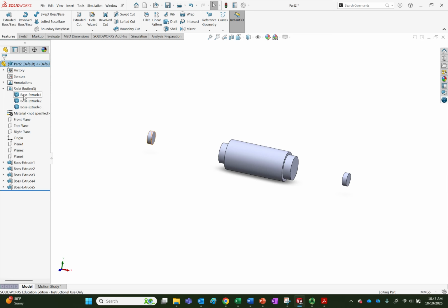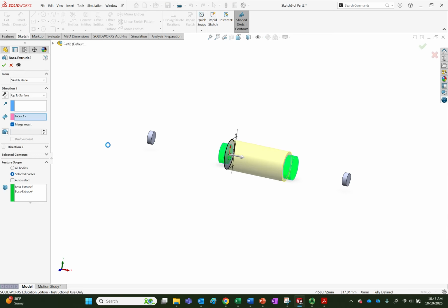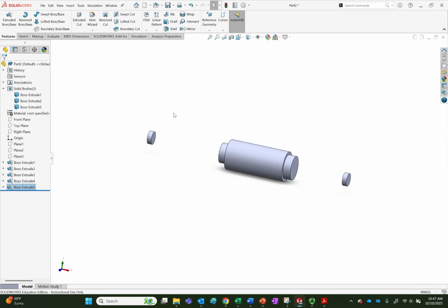So if you expanded, you could see that you have 3 separate bodies. They're not merged, but you risk when doing this approach that you didn't realize you should merge these pieces. Notably, make sure merge result is included there. Otherwise, you'll have multiple bodies. They'll be floating. Just to let you know. But see, that worked out.